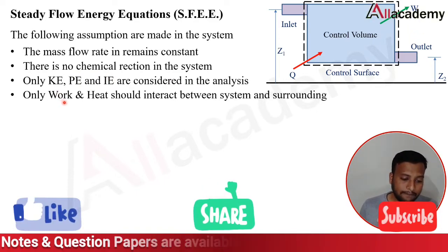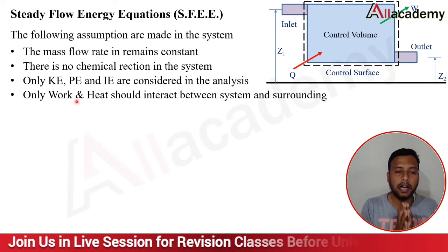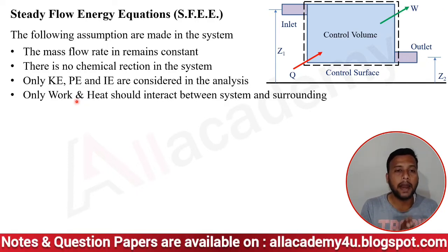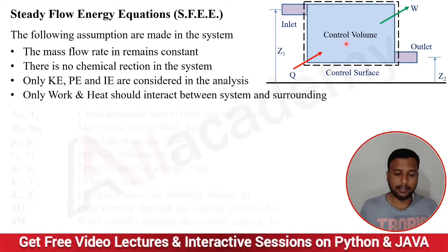Fourth, only work and heat should interact between the system and surroundings. These are the four important assumptions that have to be made while deriving or studying this steady flow energy equation. Now here you can see this one figure.